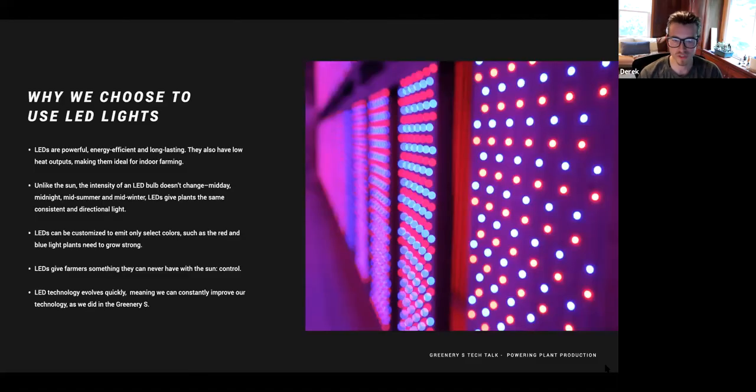And they're also quite a bit more dangerous, as they utilize a quartz envelope instead of glass, which is sensitive to temperature, oils, and touch. So you can imagine this could result in bursting bulbs or a lot of failure points. And with that tungsten filament and that halogen gas, that's not something you want in your growing environment.